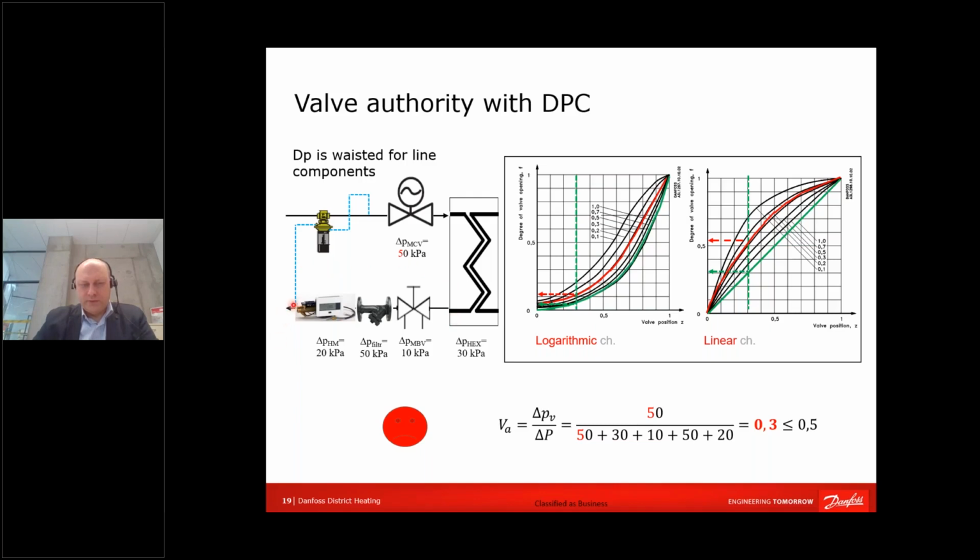What can be done? The impulse tube should be sent somewhere as close to the heat exchanger as possible, or even the best scenario would be that the impulse tube would be connected just behind the valve. I know that these schemes will be used and you will still continue using that kind.